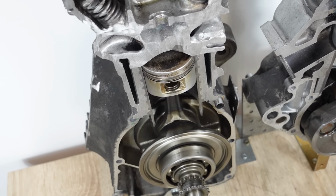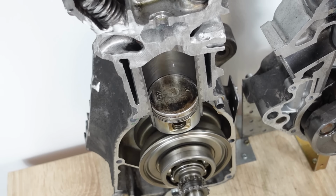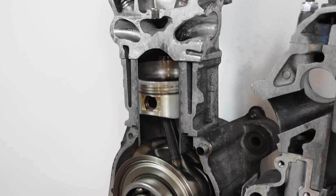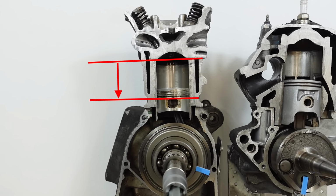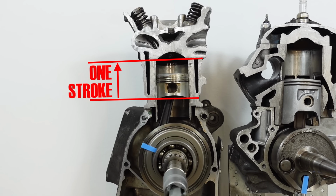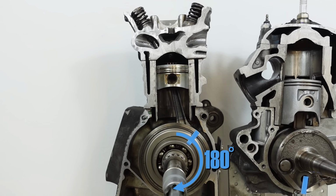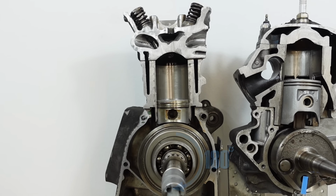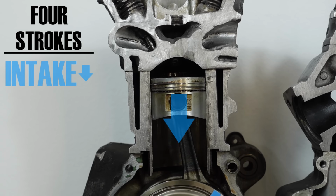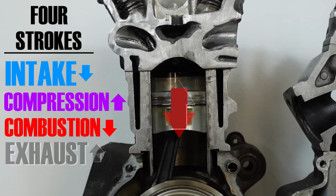Why is it called a 4-stroke? It's because the 4-stroke engine needs 4 strokes to complete one combustion cycle. Every time the piston moves from top to bottom, or vice versa, that's 1 stroke. 1 stroke of the piston equals 180 degrees of crankshaft rotation. Now the 4 strokes are intake, compression, combustion, and exhaust.